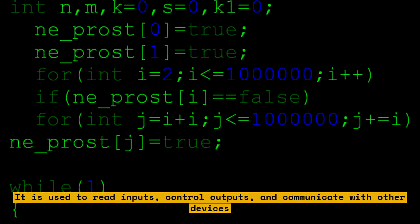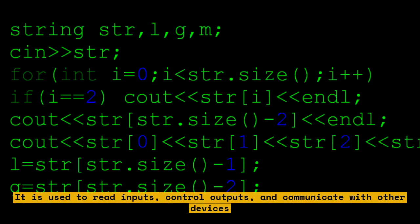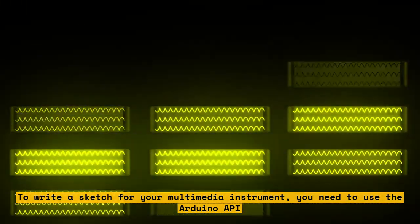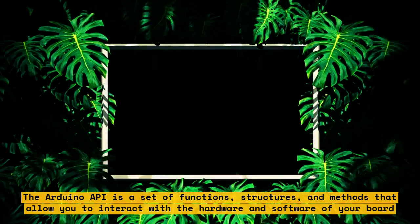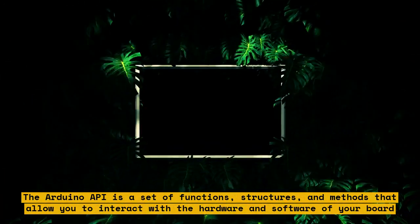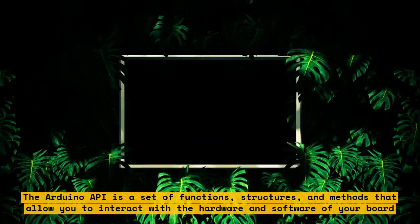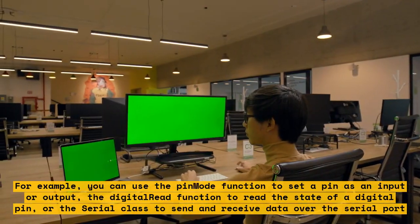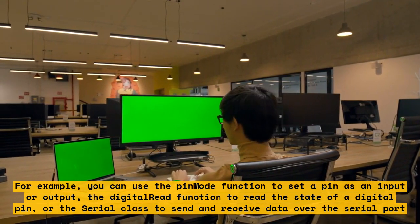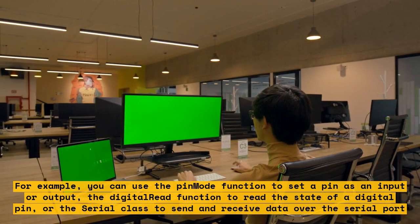To write a sketch for your multimedia instrument, you need to use the Arduino API. The Arduino API is a set of functions, structures, and methods that allow you to interact with the hardware and software of your board. For example, you can use the pinMode function to set a pin as an input or output, the digitalRead function to read the state of a digital pin, or the Serial class to send and receive data over the serial port.